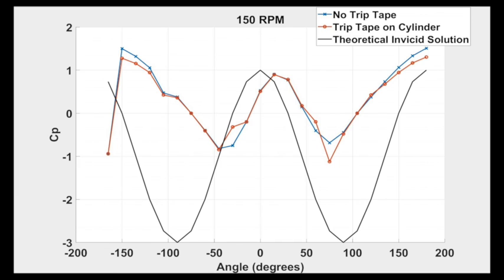Since our system forms the boundary layer, it will experience recirculation of flow when separation occurs. The difference in pressure across the cylinder will result in a drag force in the direction of flow. For our test, the data has a general shape of the theoretical solution.